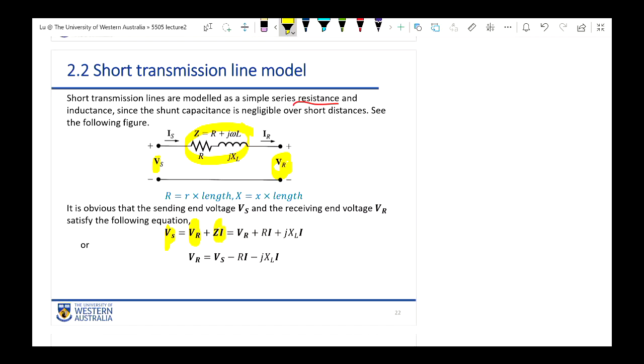Total supply is equal to the summation of the total consumption. Got that? The next step is pretty easy because we are just converting the impedance Z of the cable to R plus jXL.